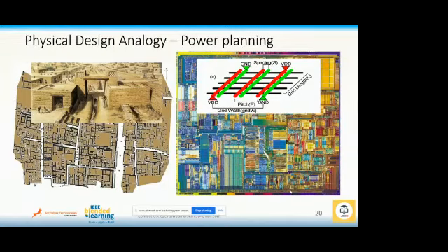Similarly, you plan the power grid in an SoC. You plan your VDD and ground signals. The entire power grid is designed before you go about placing your gates and other components. If you go next.